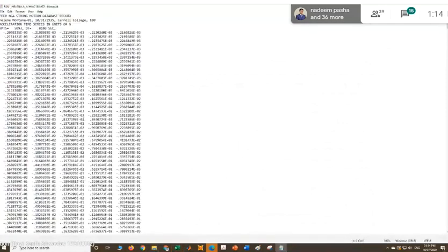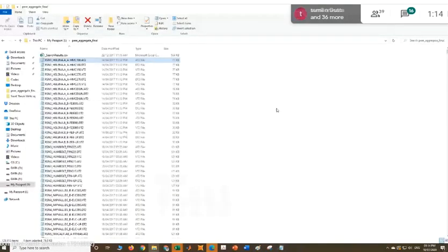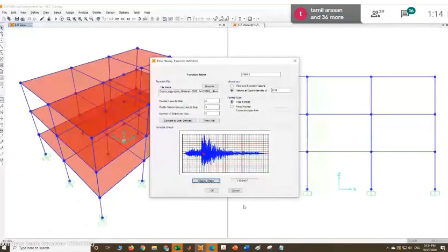Yeah, so I have selected one time history; the name of the earthquake is the 1935 Helena, Montana earthquake, recorded at Carroll College. Its direction is 180 from the north, and there are a number of points, and each point varies by 0.1 second. So these are earthquakes recorded at some different regions. So what you can do is, in time history analysis, first of all we need the earthquake recorded at the various regions.